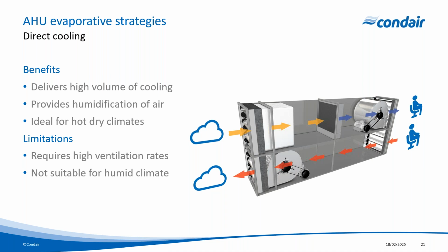And then, of course, the other consideration for this type of system is filtration. For data centers, it's important to keep outside particulate from entering the space. So filtration is always going to be a consideration when you're using a direct evaporative cooling system or strategy.